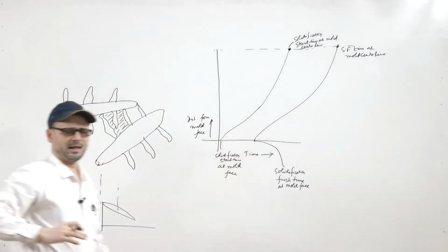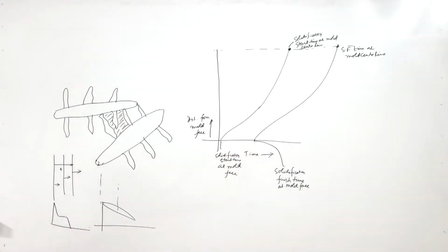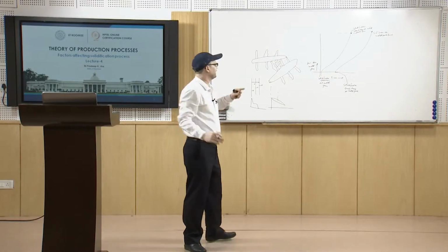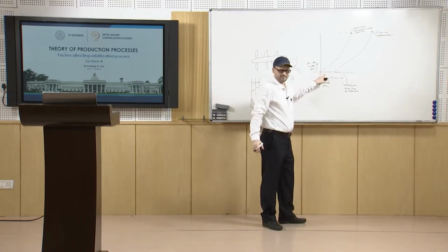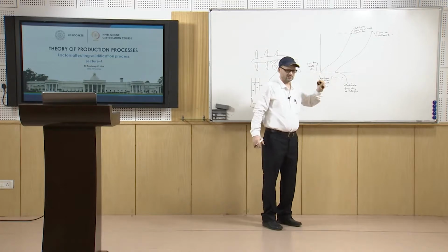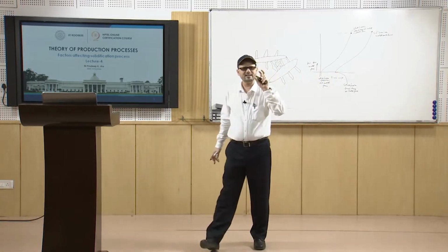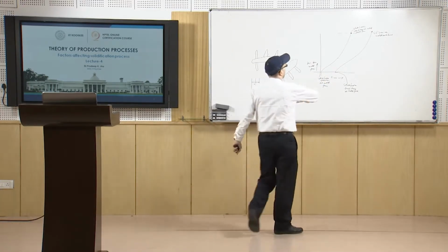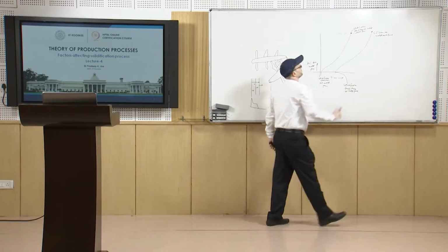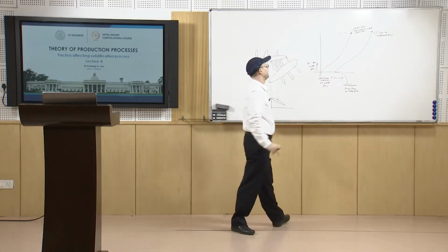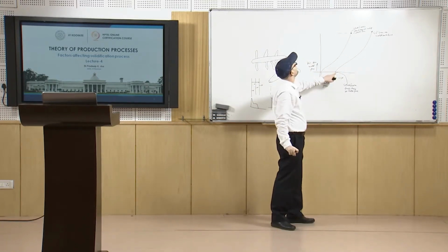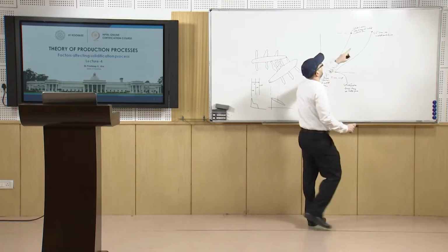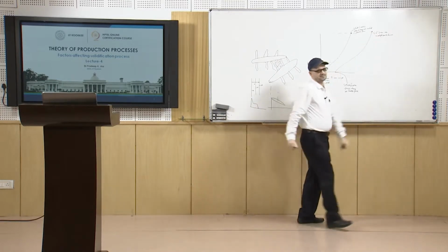So, basically what happens, it goes in a wavy manner. It starts at this place and then slowly it moves, and this is the start time. The start at the mold face will be very immediate because it will experience the largest undercooling whenever it touches the mold face, and then in this time it will start at the mold center line, whereas here it will finish at the mold face at this time, and then it will reach this point.